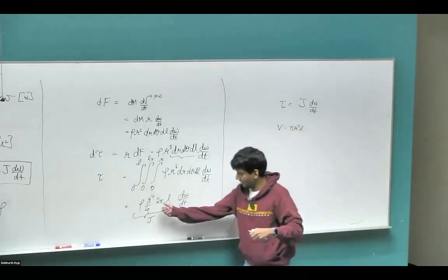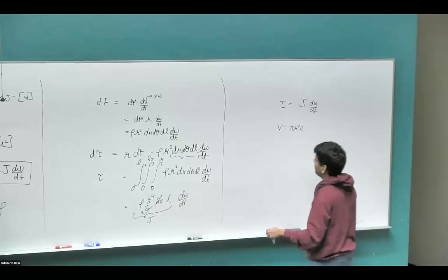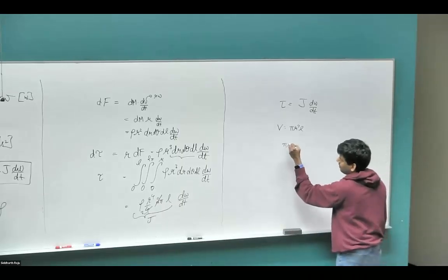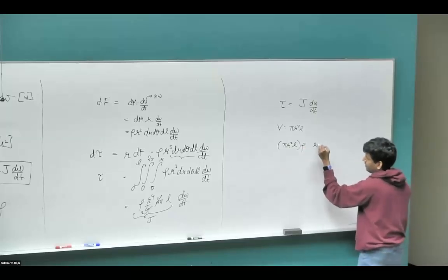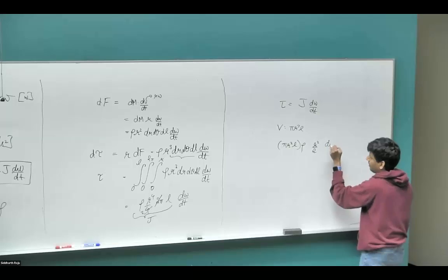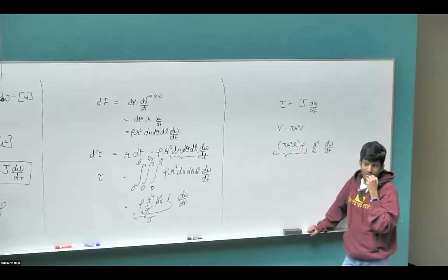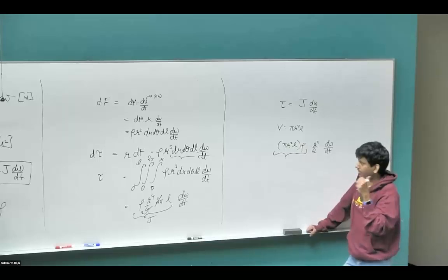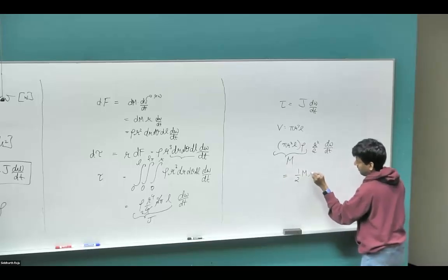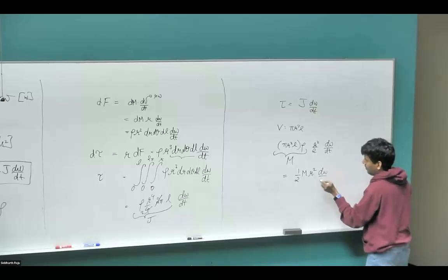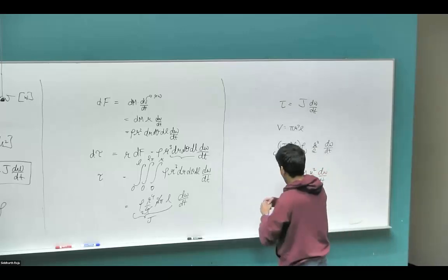So let's take out the pi r square L terms outside. So this 2, 4 cancels out. We just have our denominator 2. If you take those terms out, pi r square L times rho, all we are left with is r square divided by 2 times d omega by dt. What is this term? Mass. So that's actually going to be the mass of the cylinder. In textbooks, you might typically see this expression given for the inertia of a cylinder. So just another way of representing it.